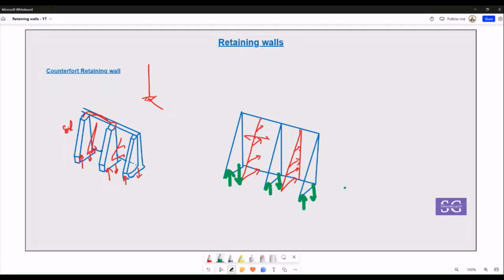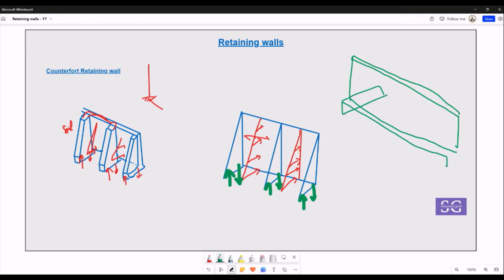This can also be done with a fixed connection. Let's assume you have a very long retaining wall that is a cantilever. You have designed it as a boundary wall, as a cantilever. Since it has such a large span, although you have designed the section along the height, it could start to deflect in the horizontal direction and give a two-way action as well.